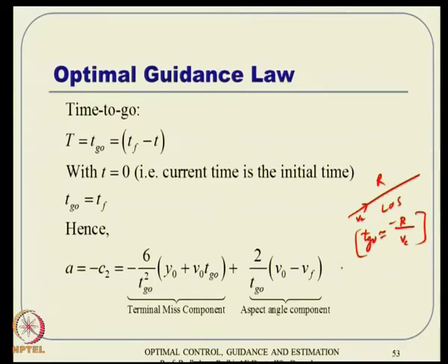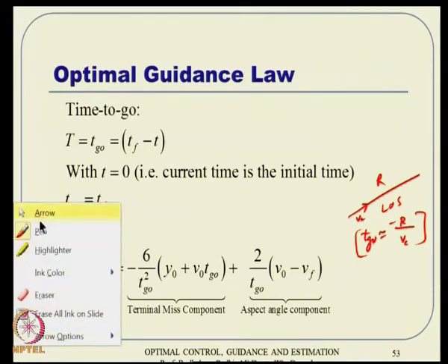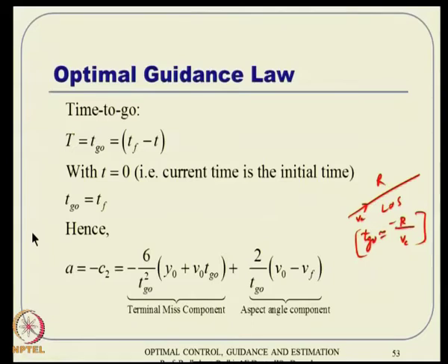but there are many different ideas for estimating this time to go in a better sense. The argument is that it is again getting updated. It is not that bad, but anytime you rely on this update sort of idea, the fluctuations will be large, and it will keep on getting different values at different points of time, and hence your entire magnitude will become different. So, your control oscillations will become more. To avoid that, it is better that you estimate a good T go which does not fluctuate much.